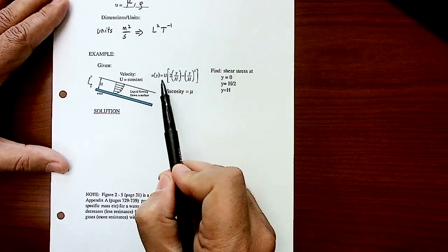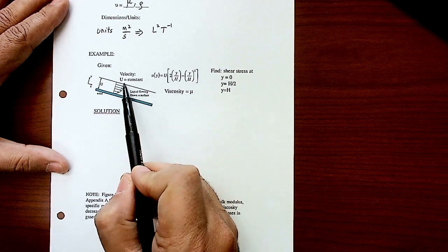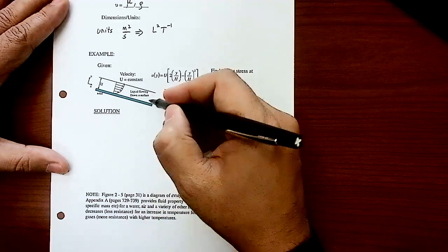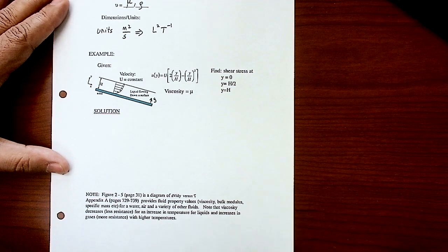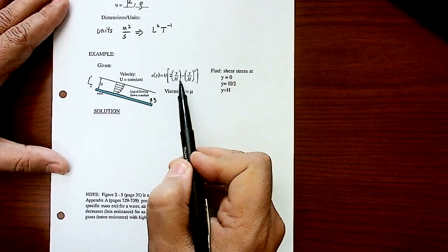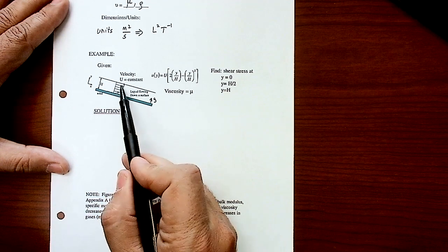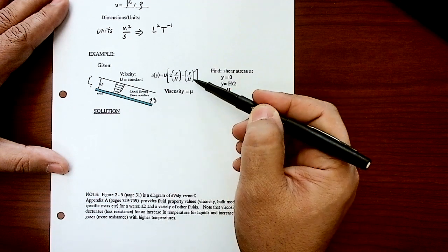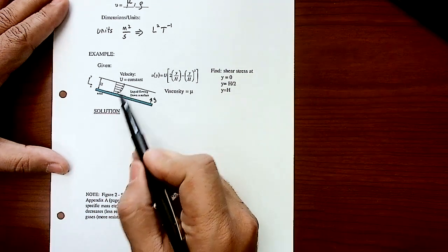And you were given an equation for that velocity distribution. The velocity at any position y equals U, which is the outside velocity here, times a function of y and h. Y is the location measured from here, and h is the thickness of this layer. So for example, if you put y equals 0, which is this face here, this term goes away, this term goes away, u is 0, right? If you put y equals h, which is the maximum height here, h over h, that's 1 times 2, that's 2. 2 minus 1 is 1 times U, so the velocity is going to be U. And anywhere in between, you put any value for y, you get the velocity distribution here.